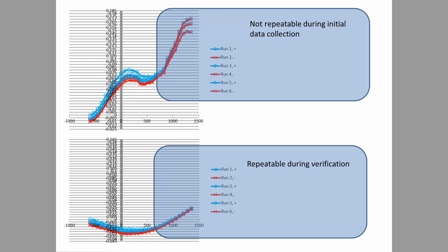So what changed on the machine, or in our laser setup, or in the physical environment that caused this repeatability to change so drastically? Did somebody close an overhead door and get rid of some wind and some air currents? We can't tell from just looking at these plots. So the point is that even though we can correct many, many good things, we're only correcting a static error. We cannot correct repeatability.